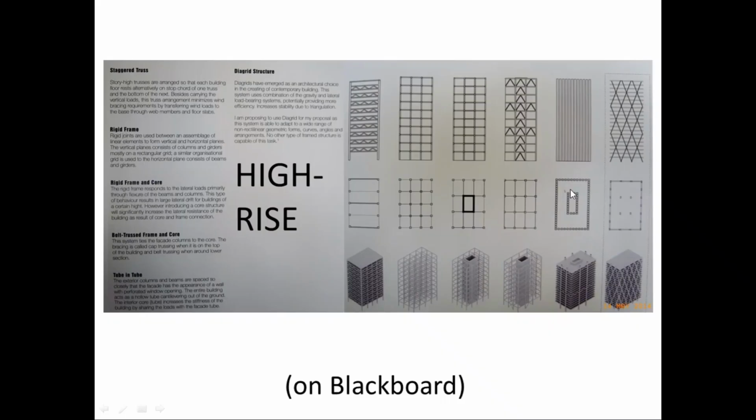This would pretty much be the design of the World Trade Towers in New York, that were very sadly the subject of a terrible disaster in around about 2001, I think it was. The reason that the building collapsed, with a high impact, of course it's not the kind of impact one normally expects, was what we call progressive collapse, if you like. Once this floor section had burnt out and the columns in it began to fail, it collapsed onto the next floor. There was then the weight of two floors that collapsed onto the third floor, and so on, and the weight increased and increased and increased.